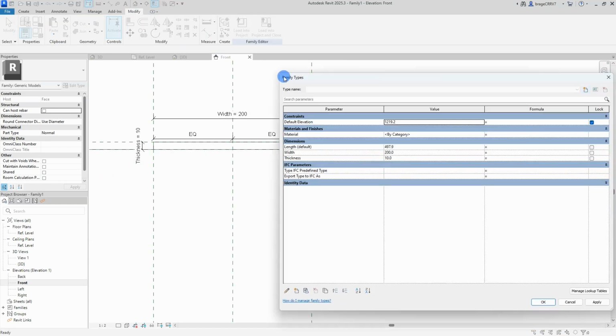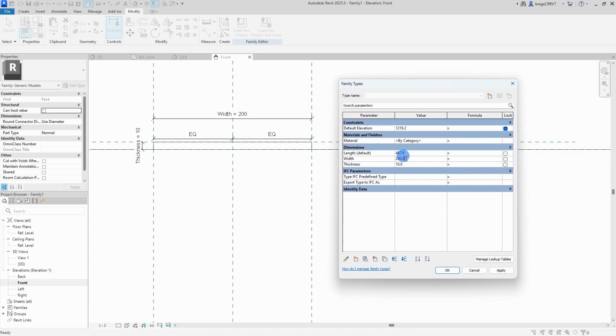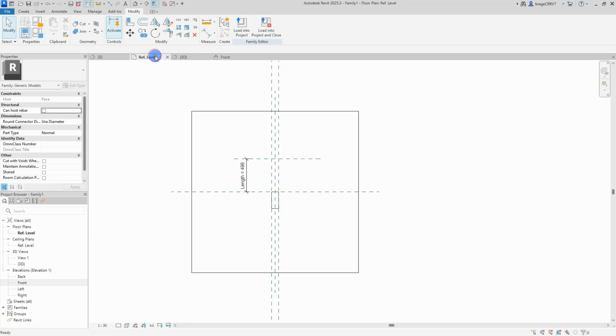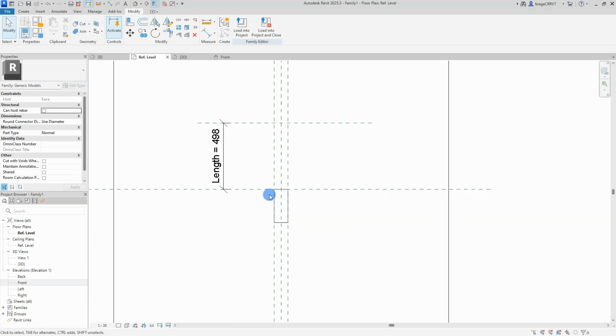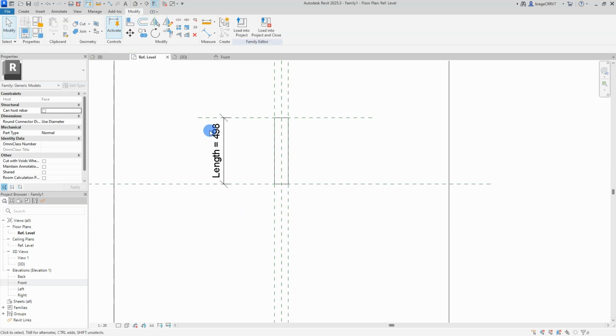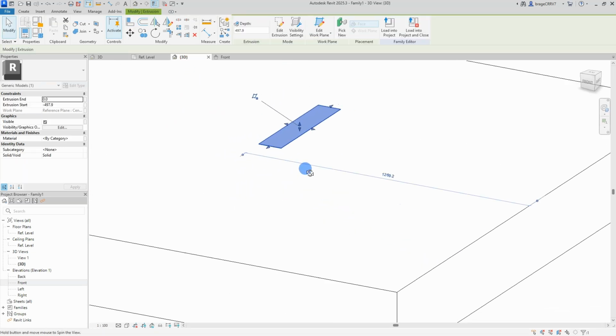I will go ahead and change the numerical parameter values to check if everything works as intended. This operation is called flexing, and I would recommend doing it regularly when developing a complex family, so you don't end up at the end with a highly advanced family that doesn't work. Gonna be a nightmare to find the errors. Forgot to constrain the length of the geometry. Quickly do that. I would also like to connect the material parameter to the object.